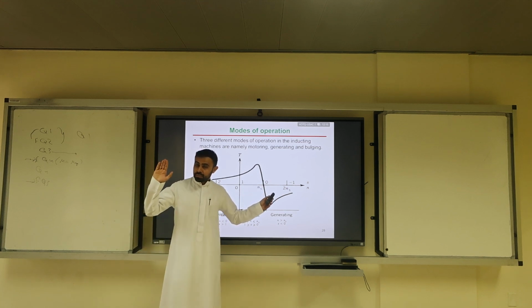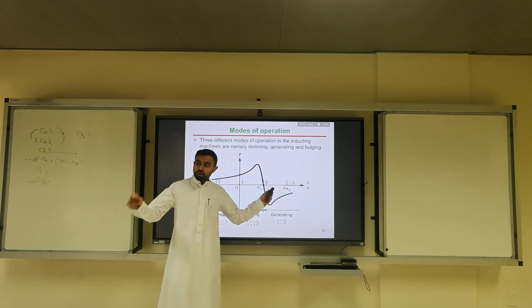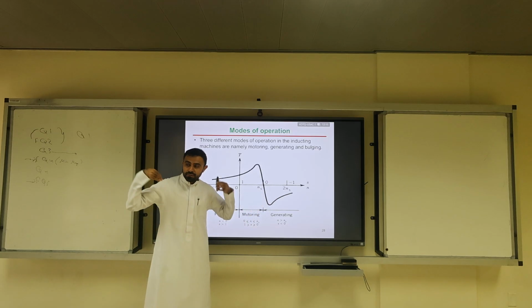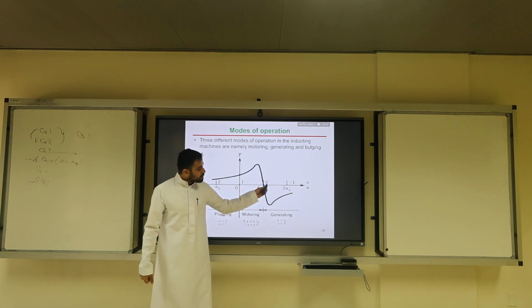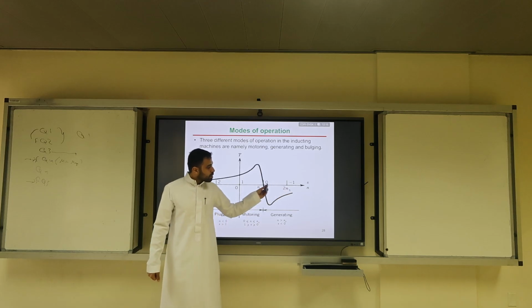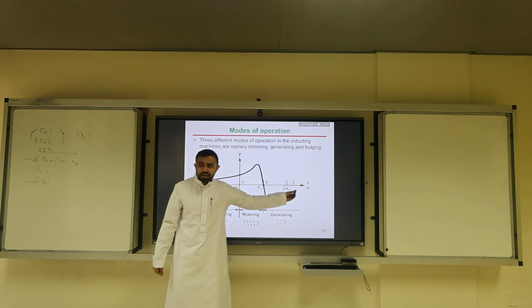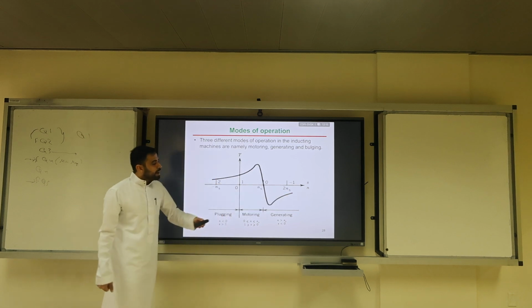Because when you hit the pedal for EVs, you're controlling the signal. You're actually having control in your machine. But if you leave it free spinning, it will increase the speed of the rotor shaft above the synchronous speed, and now you will be generating electricity.